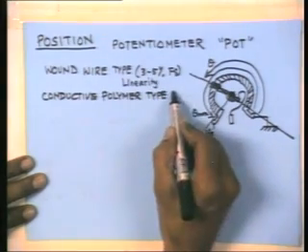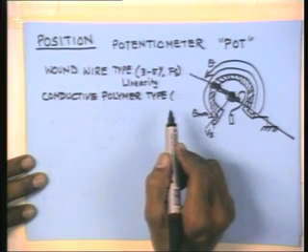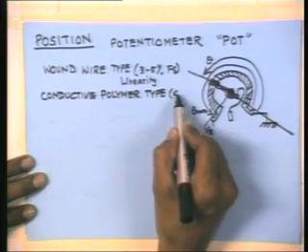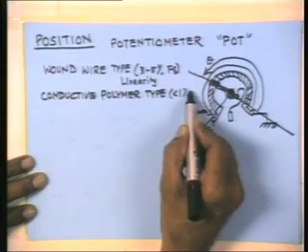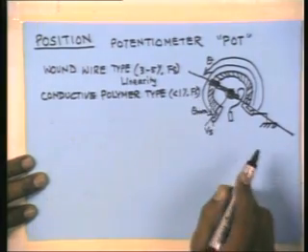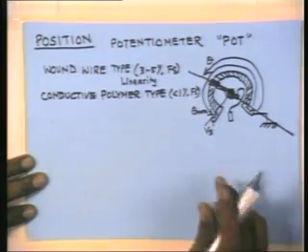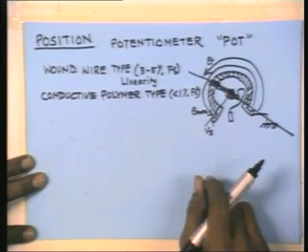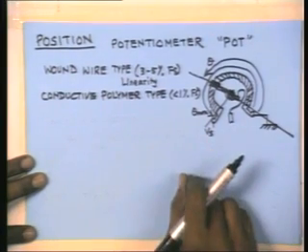They can give you a fraction of a percent, less than 1% of full scale. So there we are coming down to a couple of degrees or a degree in terms of linearity. There is also the problem of noise because there is a moving contact, and although the noise problem is much reduced in the conductive polymer type, it has some kind of a damped response compared to the wire wound.